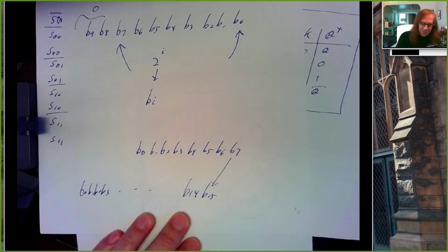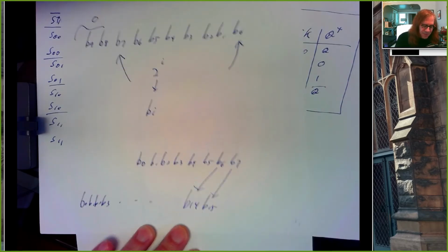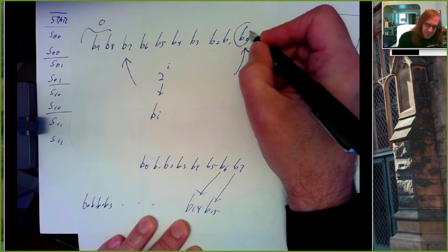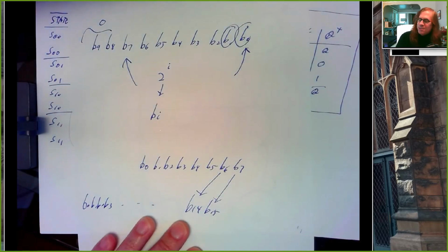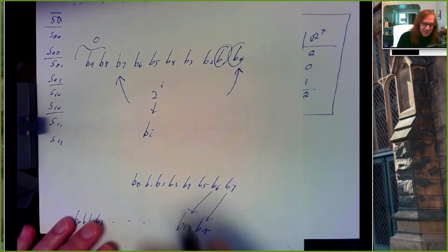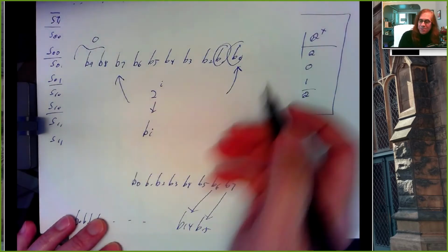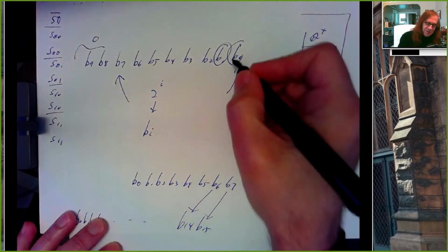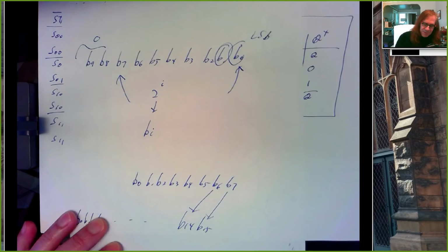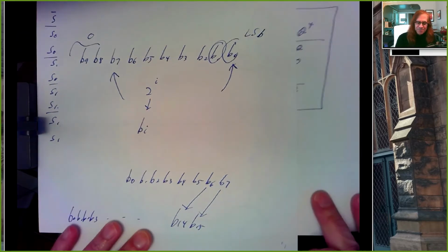Bit 7 would become bit 15. Bit 6 would become bit 14, and so on. Whereas here, if we had a 16-bit number, bit 0 is still bit 0, bit 1 is still bit 1. So that's one of the reasons that in computer science we number the bits starting with a 0 on the right. The least significant bit is bit 0.